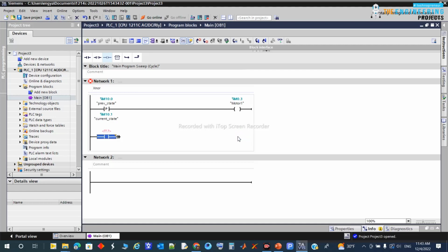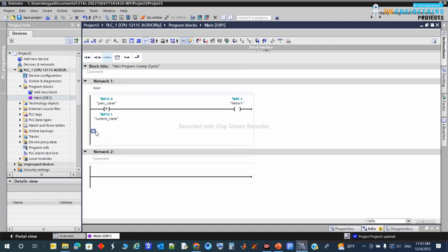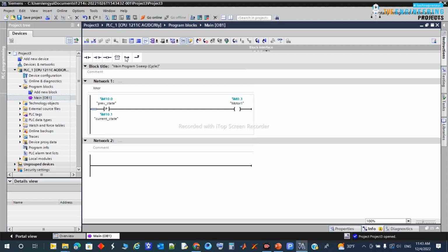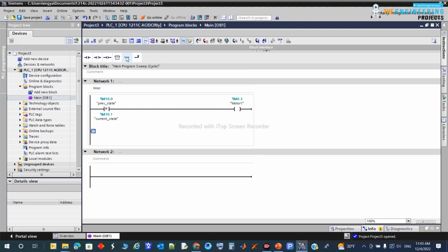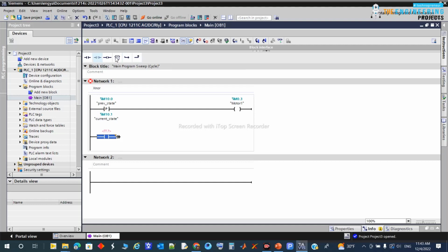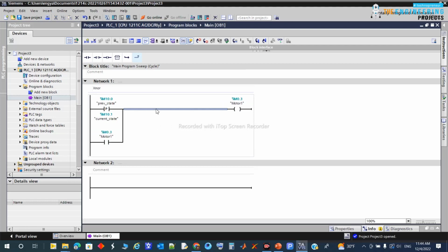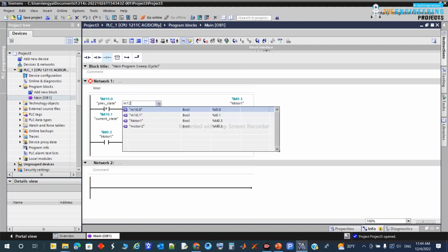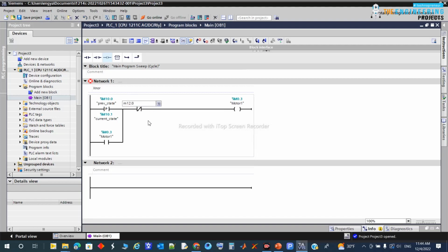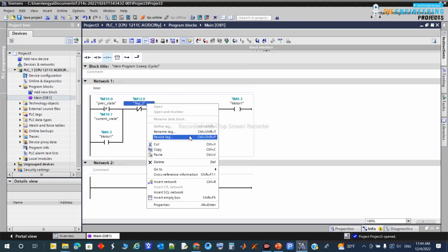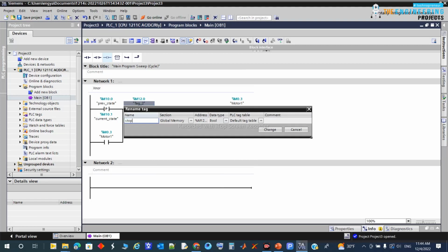Or we can simply make a contact here. So we can make another latching like this. Okay, and take this one here. Okay, and make stop here like M to 0, and I will use this for stop the motor. So I will cause this one to stop the motor.